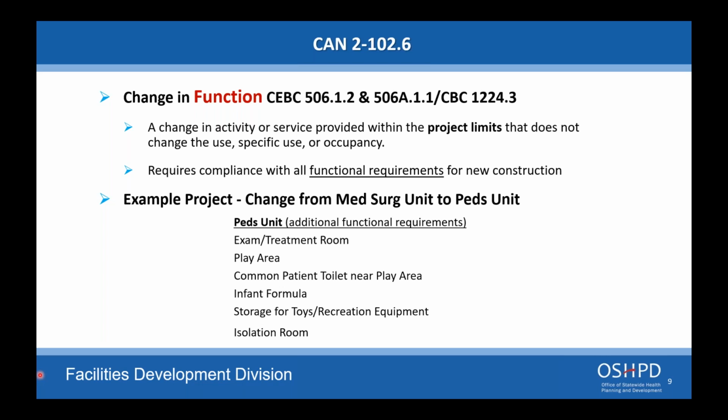If you're switching from a med-surg unit, remodeling it to a pediatric unit, the pediatric unit has additional functional requirements. It requires an exam and treatment room, a play area, a common patient toilet near the play area, infant formula, storage for toys and recreational equipment, and isolation room.